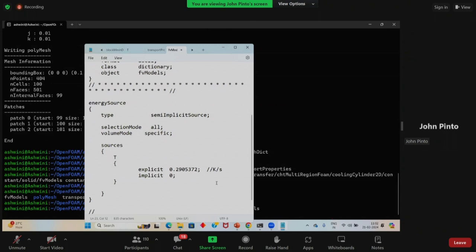Okay. So SP is your implicit contribution. Implicit contribution comes in whenever that is also multiplied by the source. Like say if this also depends on your temperature, then it will be this into T. Right now we don't need this contribution, so that is zero for us. Most of the time you will use only this explicit contribution, only for very specific cases.